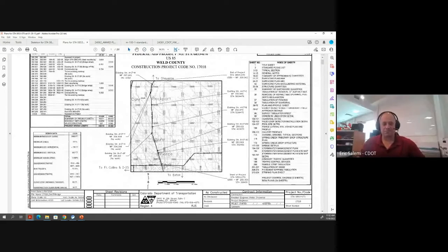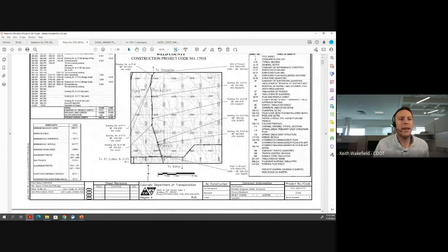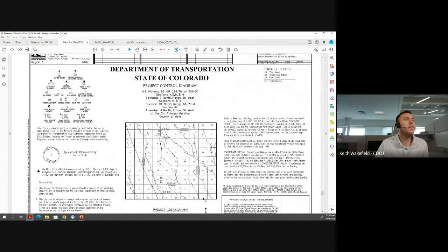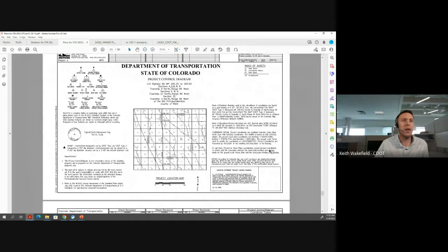I was just going to say, let's look, right-of-way plan sheets are at the very end. So we're going to go to page 255 to pull up kind of what a general right-of-way plan should look like. And it provides the survey information for the project. There are templates, and there's a pretty specific process as to what right-of-way sheets should look like. Now, I think it does vary from region to region as to what their requirements are. I know, for example, Region 4 might want things to look a little different than Region 2, but for the most part, they're pretty similar.